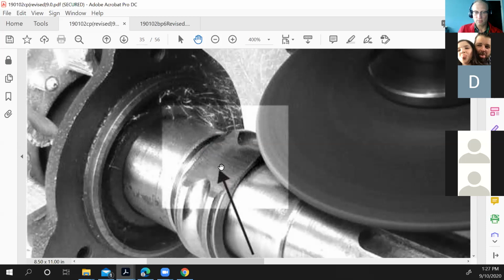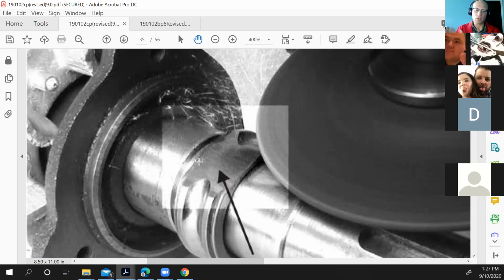The idea behind moving fairly quickly is that the heat is going into the thinner material and it doesn't have the chance to transmit into the thicker, larger piece of steel. And you're cutting the smaller one away faster than it can transfer heat. So that other piece should be quite a bit cooler. But if you've put heat to it for a long period of time and you go cut it, it's all just gonna turn to slag right away.